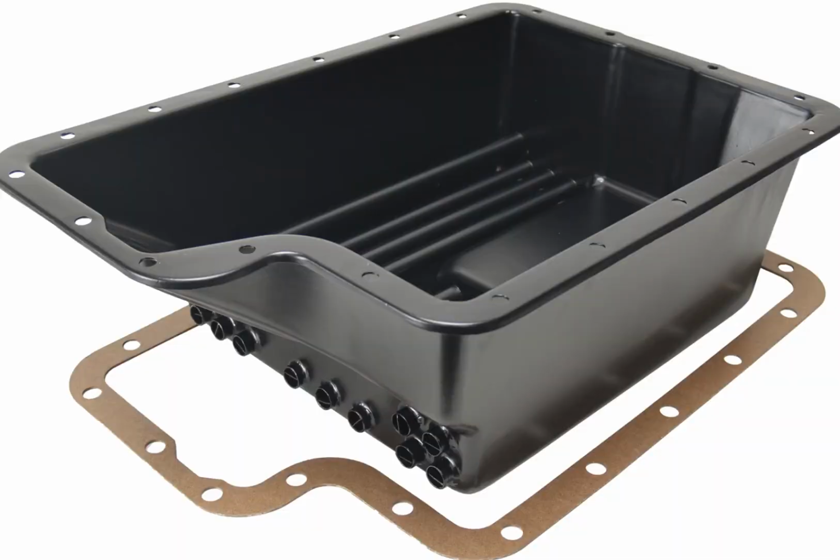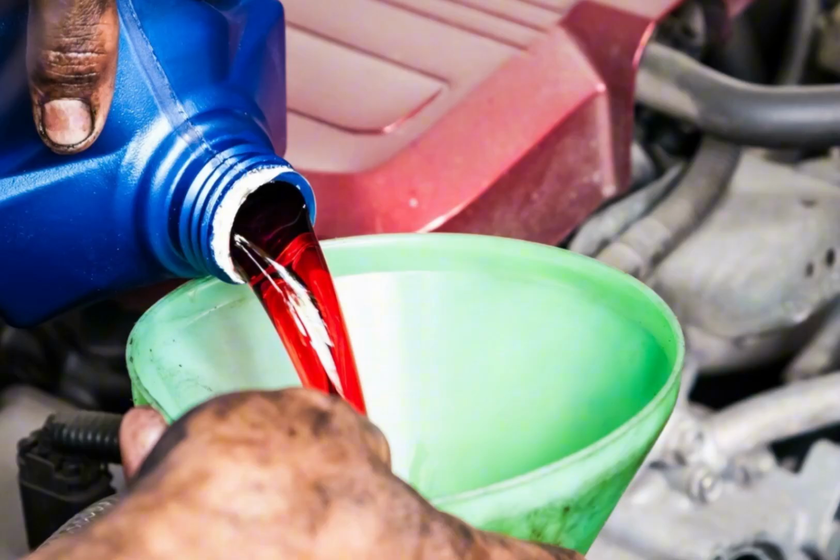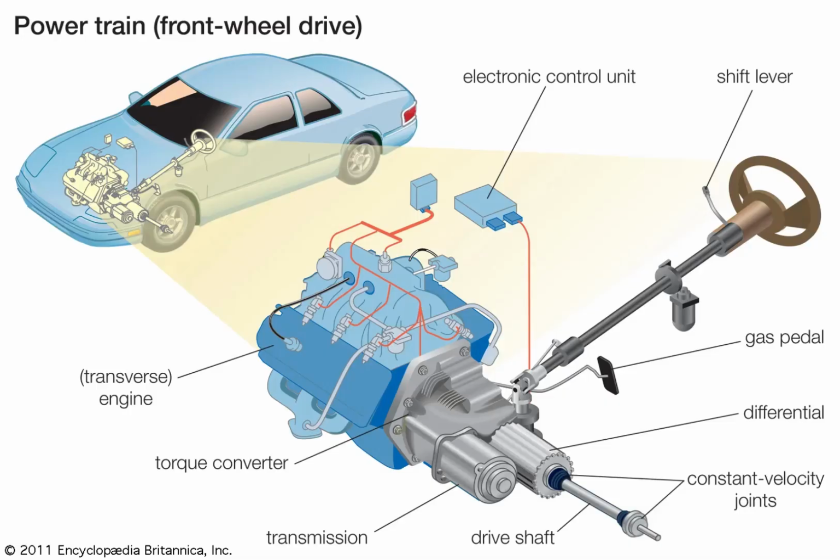Replace the filter. Unscrew and replace the old filter. Inspect the pan and magnet. Clean the pan and check for metal shavings, a sign of wear. Refill with transmission fluid. Pour in the recommended type and quantity of fluid using a funnel. Test drive. Ensure smooth gear shifting and no leaks.